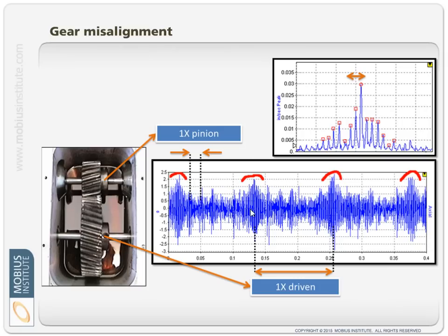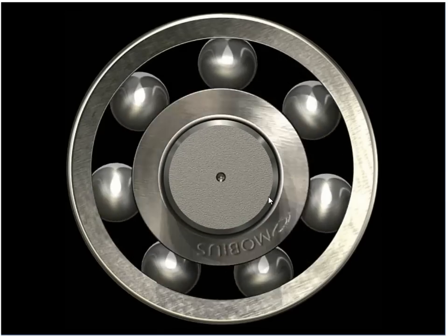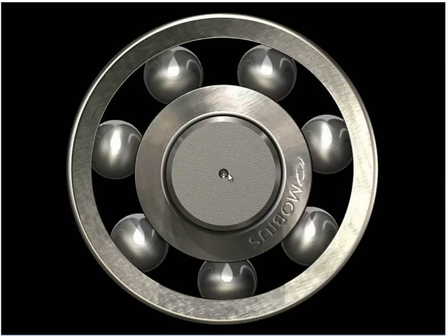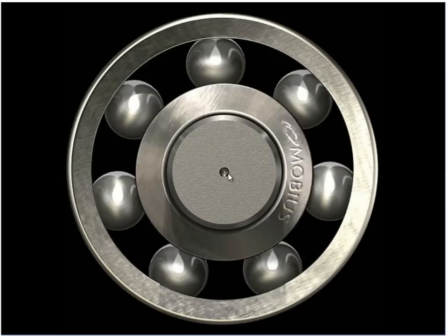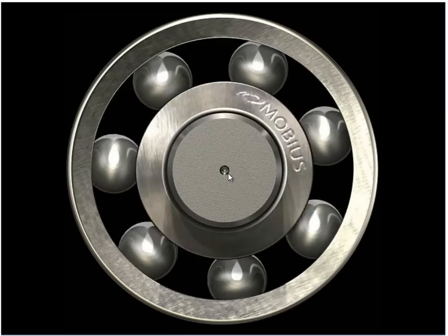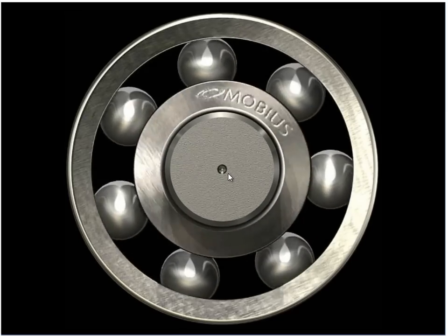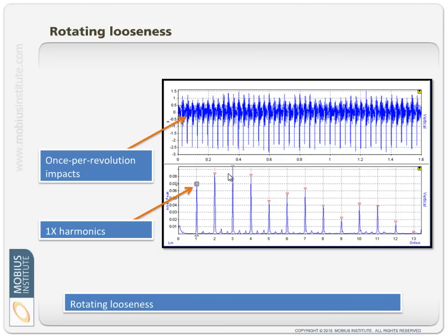When we look at the time waveform, it's telling me exactly what's going on. Here I'm showing looseness. There's the bearing sort of rattling around, or the shaft with the inner race. If you look closely, it's sort of rattling around because there's too much clearance, and maybe there's some unbalance driving that force, that motion. And here is the spectrum. I mentioned it earlier. We've got a lot of these peaks. That's the running speed, twice running speed, 3 times. These are harmonics. So sure, I would see that, and in this instance I'd probably think it was looseness.